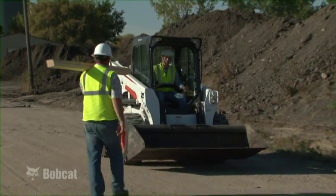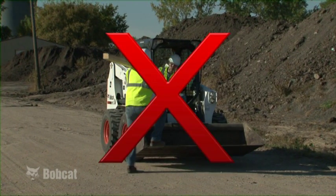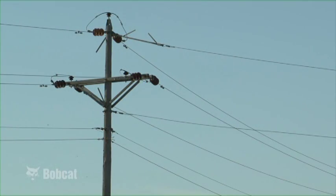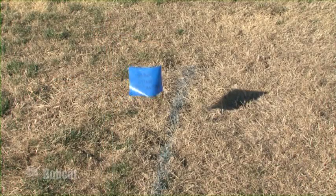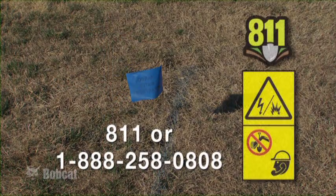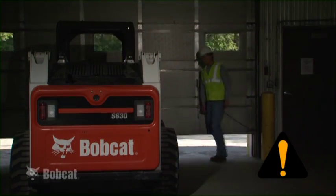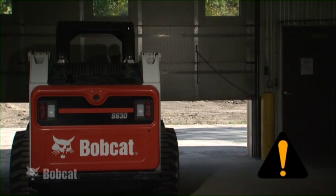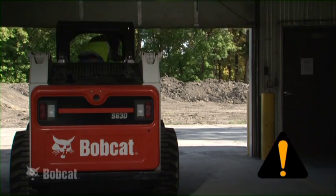Never carry riders on the loader or on attachments. A Bobcat skid steer loader is strictly a one-person machine. Be aware of potential job site hazards, such as overhead or underground utilities. Call before you dig. If you must work in an enclosed area, make sure you have adequate ventilation. Exhaust fumes can kill or cause serious illness.